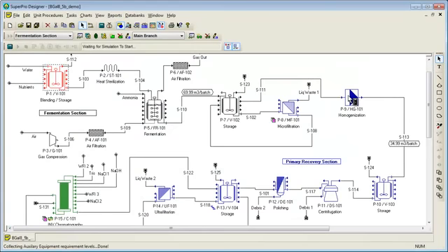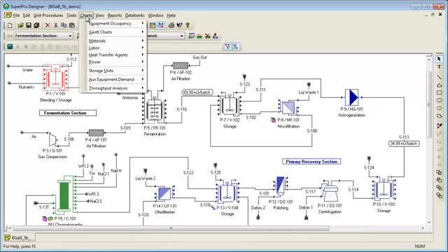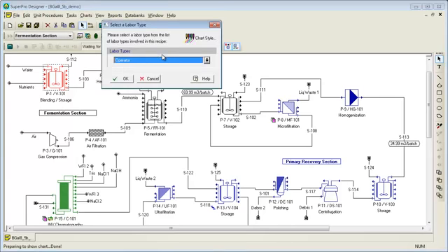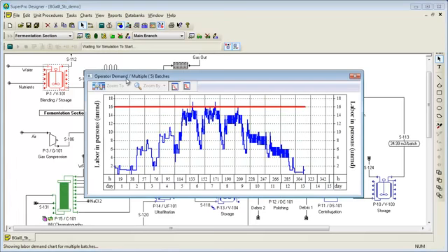In addition to scheduling of main equipment, it may be necessary for you to track various resources associated with your process. To facilitate this, SuperPro can create charts showing material inputs, inventory levels, product generation, waste generation, utility usage, labor requirements, and cleaning equipment over time for either single batches or multiple consecutive batches. For example, this particular chart displays the demand for operator labor as a function of time for 5 consecutive batches.